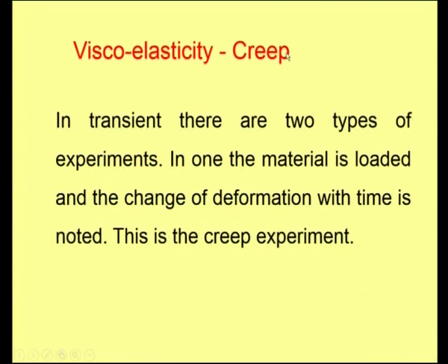In transient experiments again there are two different properties that are analyzed. One is creep. In one the material is loaded and then the change of deformation with time is noted. This is the creep experiment. So here load refers to the applied stress, applying some stress and then plotting how the deformation changes with time, which is called as creep.